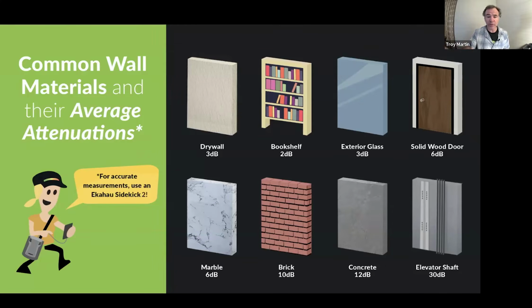Now you could go to site to help reduce some of your risk. You go to site with some sort of access point, you set it up temporarily, and you take some spot check measurements of the walls that allows you to characterize some of those wall types. But as you do those spot check measurements, you may only be measuring one portion of the wall, right?